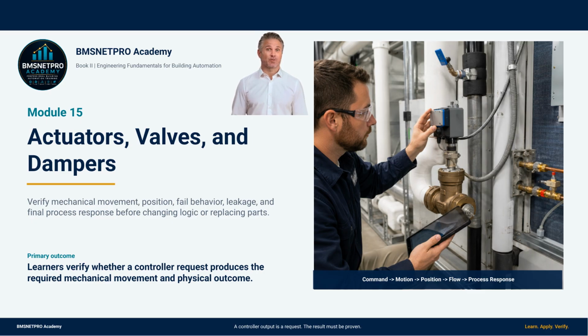A valve command is not flow. A damper position is not ventilation. An actuator moving does not guarantee the stem, shaft or blades moved correctly. In this lesson, we will build the field habit of verifying the entire action chain: command, actuator motion, linkage, valve or damper position, flow or airflow, and process response.